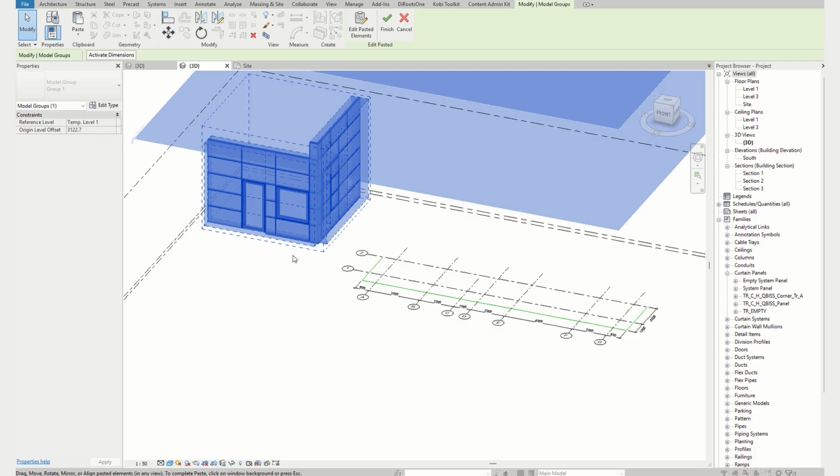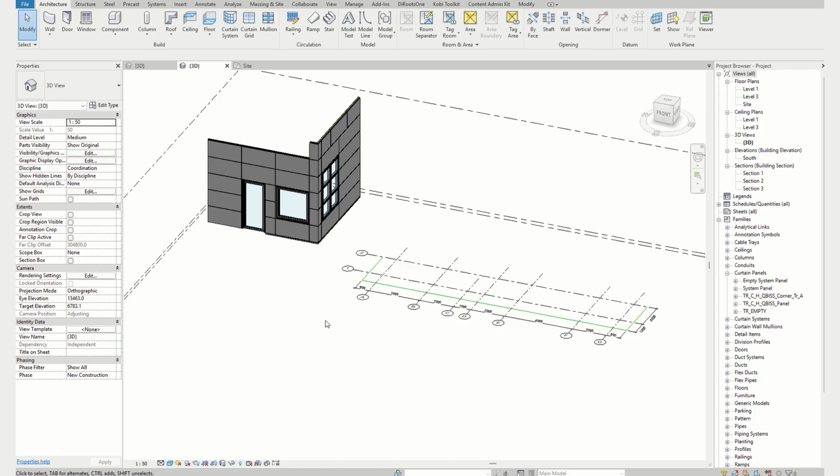We recommend keeping the start file opened in the background. This way we can easily copy any missing family settings or schedules whenever we need them. So not all families get copied automatically. No, only the currently used families and the types used in these families are copied for now. This keeps our list of families shorter and easier to manage. Later in this session, we will show you how to add any missing families or settings.